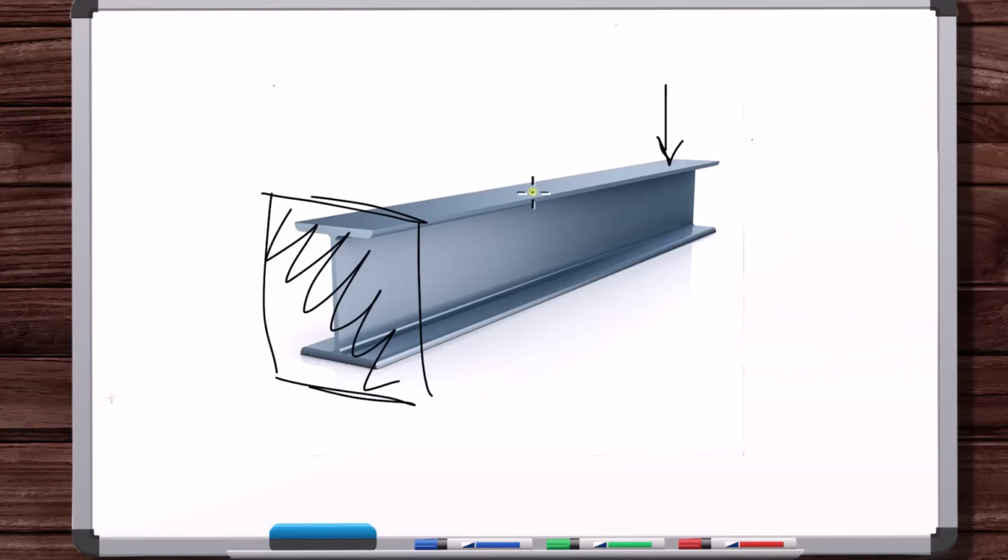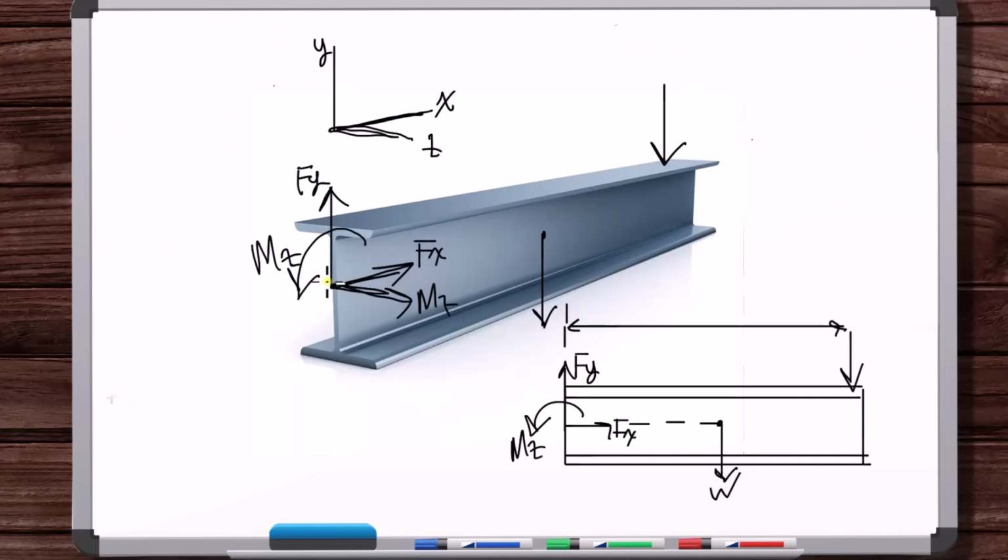Well, what about the forces in that plane there? Where did those go? Don't we need to add those? Don't we need to, on our free body diagram, so we add the bolt forces, don't we need to also add those forces right there? No, because for this free body diagram, those forces are internal forces. And so from that standpoint, you could kind of look at it like, for this free body diagram, these aren't internal forces anymore. These are more external forces, right? At least for this free body diagram.